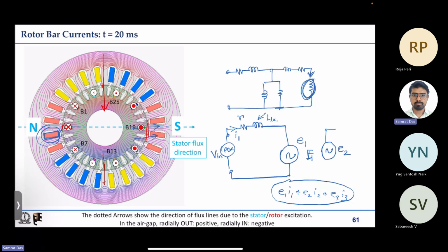Means if we have a rotor bar like this, there will certainly be some currents which flow only enclosing that bar and will not cross the air gap to cause flux linkage of the stator winding. That is what is known as the leakage flux. So there will inevitably be some leakage flux of the rotor also. Basically the leakage flux is responsible for some leakage inductance, and there is some resistance of the rotor bars also.